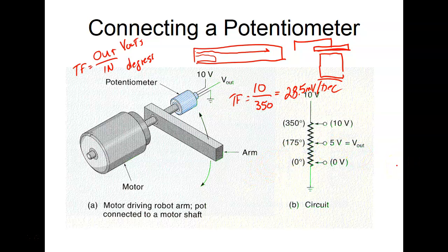And the size of the pot, the ohms of the pot, really doesn't make any difference, right? You understand? It's just that the smaller the pot is, the more precise it can be. So if I had a 10K pot, then that's going to be volts per 10K. It's going to be harder to adjust than a 1K pot. And a 1K pot would consume more power just sitting there by itself.